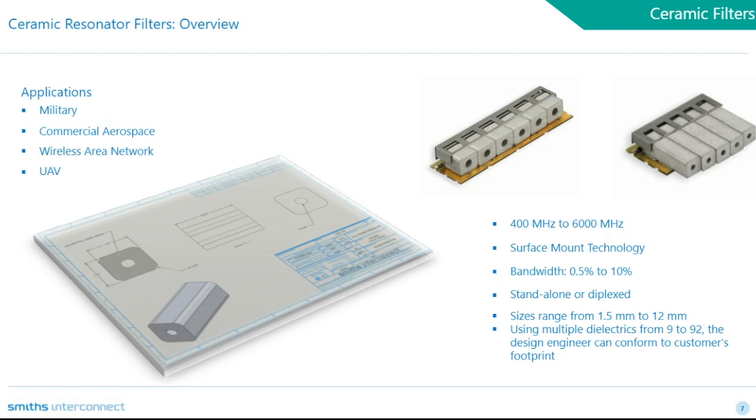And while printed filters command attention today by their incredibly small envelope, ceramic filters will still offer better performance generally at a similar price and quantities. We will go into further detail a bit later, but I wanted to set the tone for why this topology is an excellent in-between, quote-unquote, solution when performance, price, and size are all important to the customer.